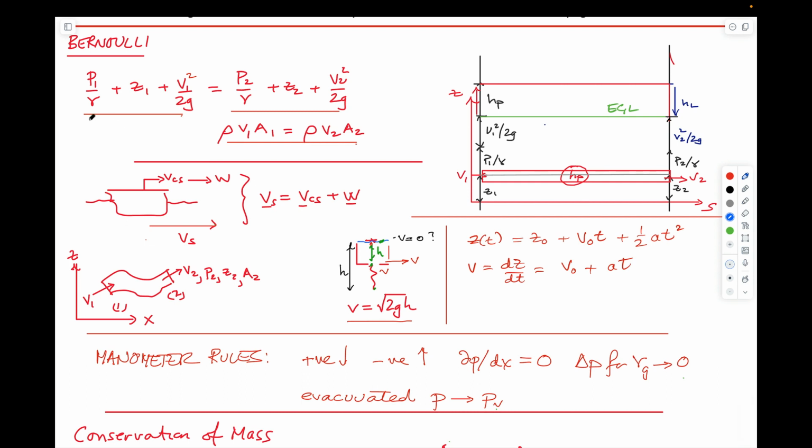You know Bernoulli's relationship. You write it from upstream to downstream for these 6 parameters. It doesn't matter that it has to be upstream and downstream, but it's easy just to use that convention. If you have 5 knowns and only 1 unknown, you can solve it directly.